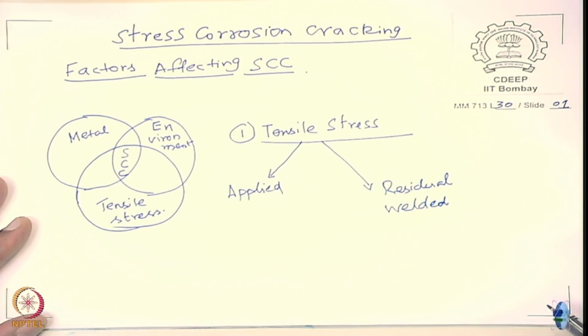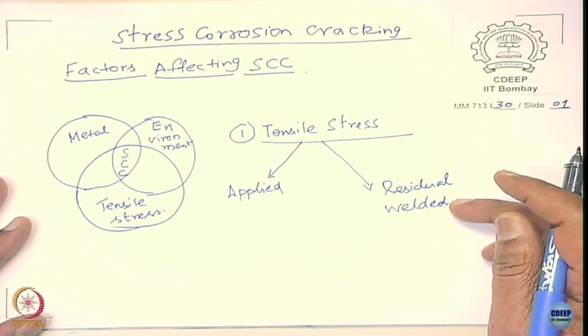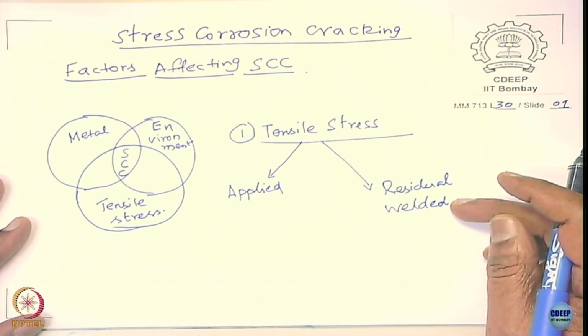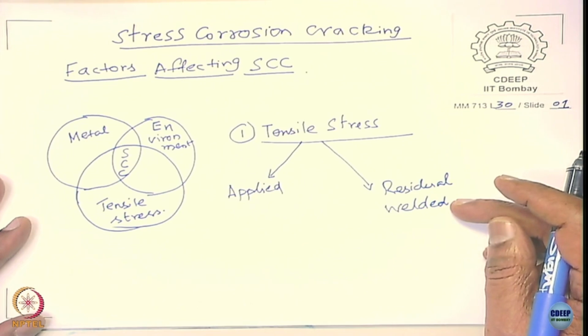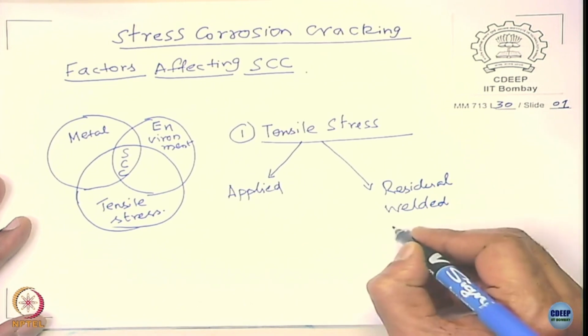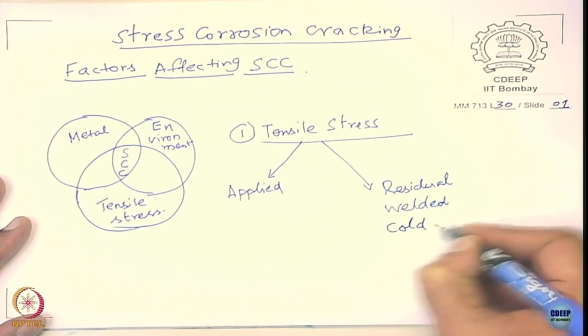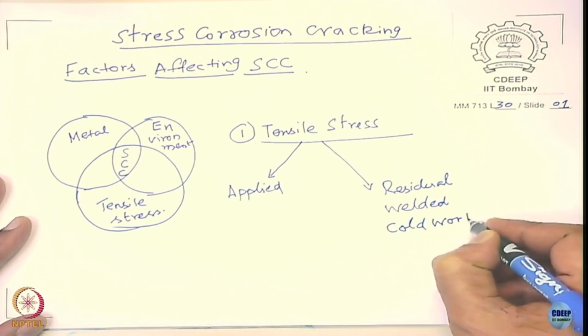You weld it, and the weld zone could have a tensile component, and somewhere in the weld component you can also have a compressive component. So, there are residual stresses acting even when you remove all the external loading or stresses onto a component. It could be a cold work.